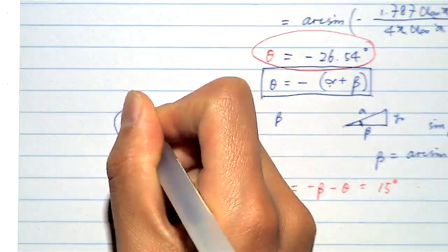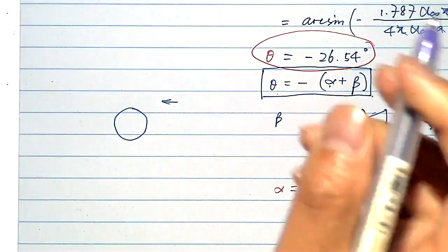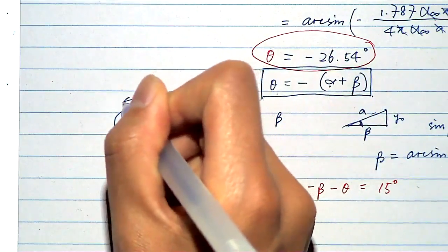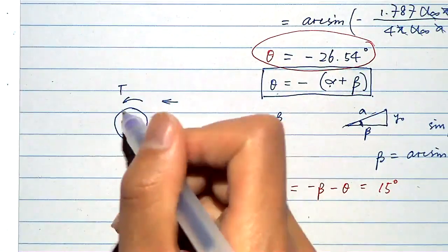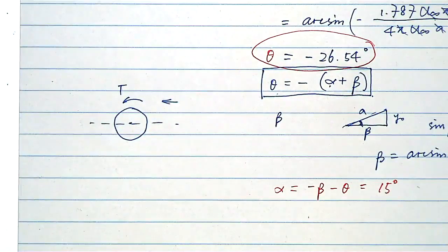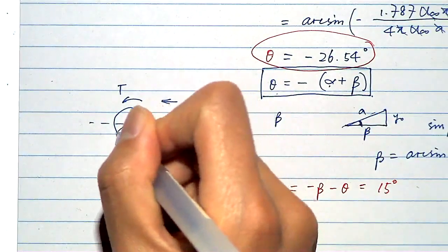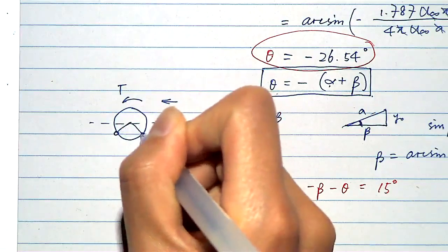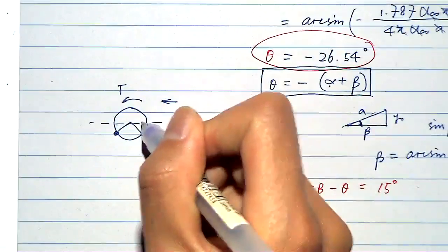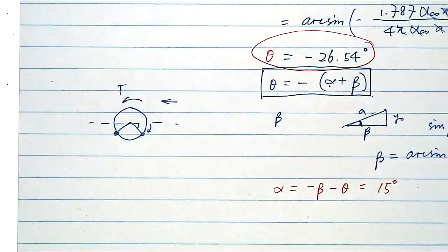this is a cylinder, and we have the flow coming this way. So if there is a positive circulation, let's say positive circulation means it's rotating counterclockwise, the two stagnation points would be moved downward. So these are the two new stagnation points moved from here to here. And the angle, if we look at this one on the right, this is usually how we define theta.